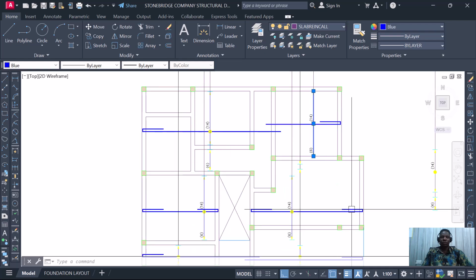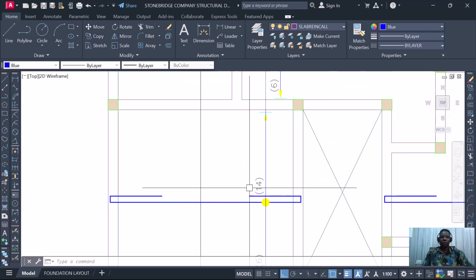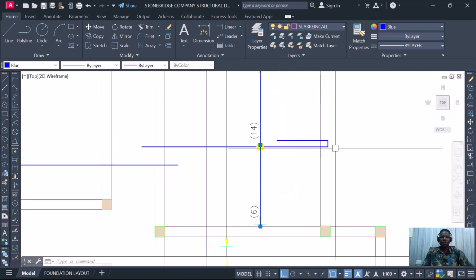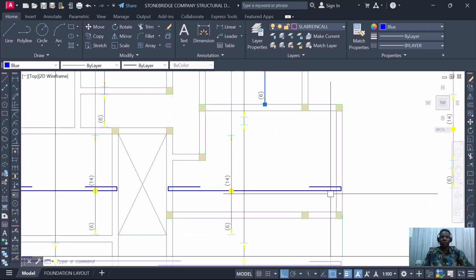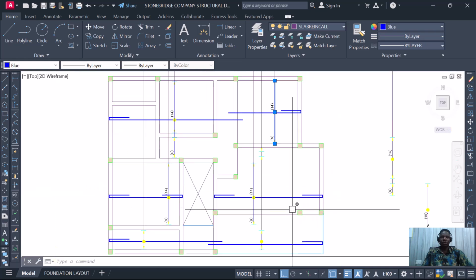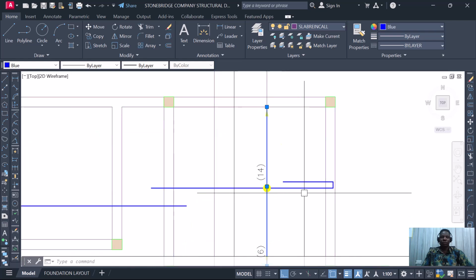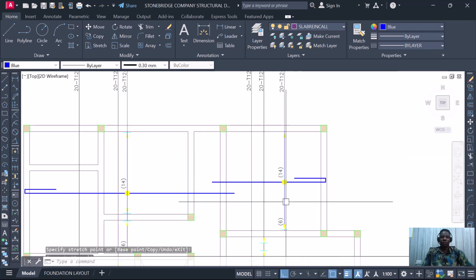All right. So if you look at what we have here now, since here is an endpoint, we don't have any slab here. This bar, this reinforcement is meant to what? It's meant to return. Forget the fact that I have this particular panel. It's as if I'm using the same return length to do this other one. Like this particular panel is also higher, so I'm supposed to use the return length for this panel.